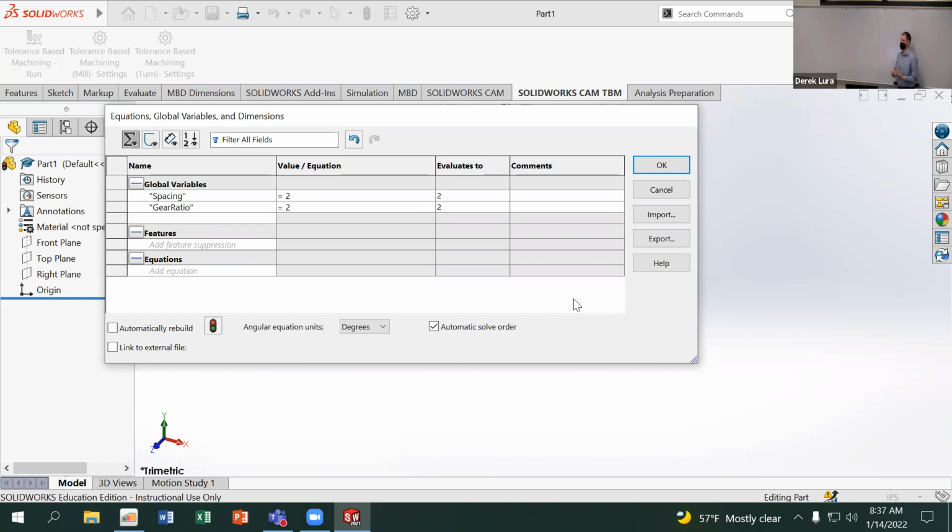Spur gears, which is what we're making, are reasonably good at a range of gear ratios that are not extreme, right? So 2-to-1, 3-to-1, 4-to-1, 5-to-1, or something that's closer to 0.5, the inverse of all those, all work pretty well. You can't make the smallest gear too small.